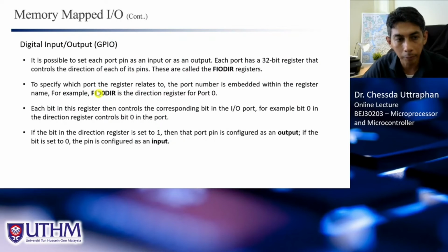How to configure the port? We need to use another register in the I/O. This is not in the microprocessor, but a register in the I/O. This is called the data direction register, or the direction register. In ARM, in LPC1768, the name is the FIODIR register.